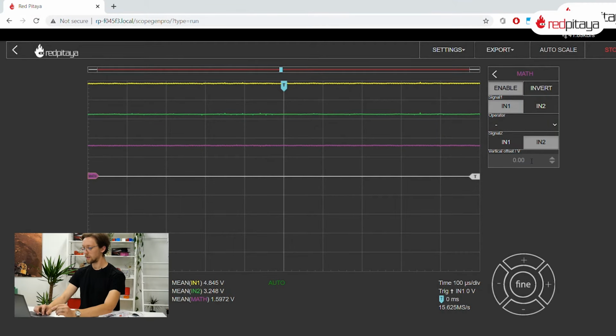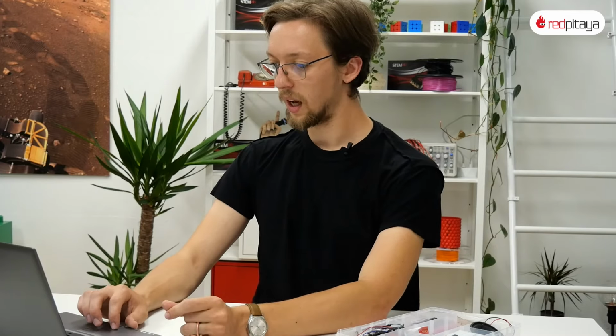Okay, let's first take a look at sources of error. Firstly, input 2 is poorly calibrated. It shows about 0.13 volts too high, but this isn't all. If I measure voltage on 5 and 3.3 volt pins, actual voltages are off by quite a bit. So I have to rerun the calculation with those numbers. But simply entering numbers in previous equations is prone to making an error, there must be a better way. After all, I hinted at the simplification in the intro. Let's take a look.